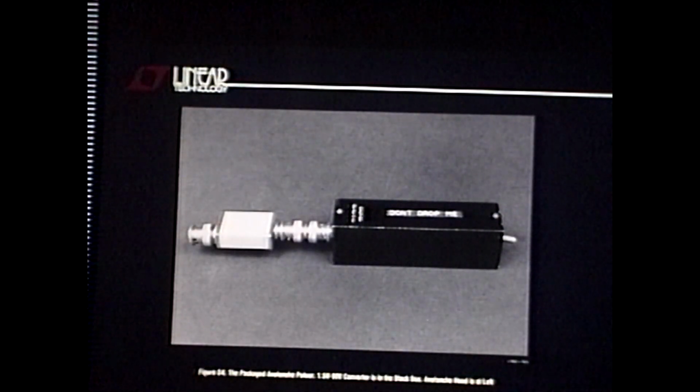That's what the thing looks like when you're done. It's just an old busted probe piece with the actual avalanche head, and in here there's a 1.5 volt regulator and the 90-volt switcher. That's it. So you can walk up to the circuit anywhere, BNC your way in, and stick this edge in and say, what is my probe circuit test measurement setup doing with this edge? How much can I believe?